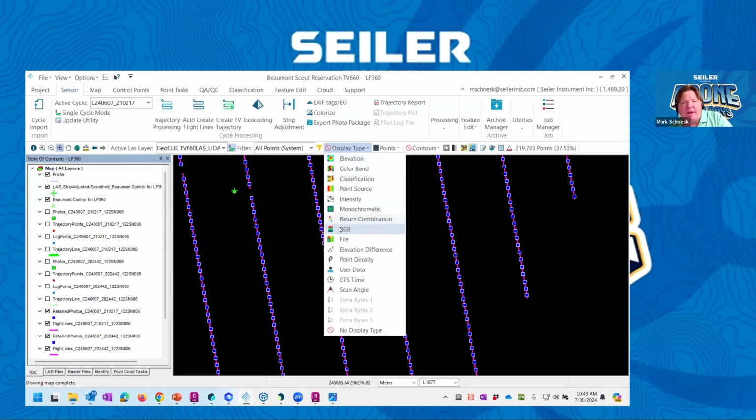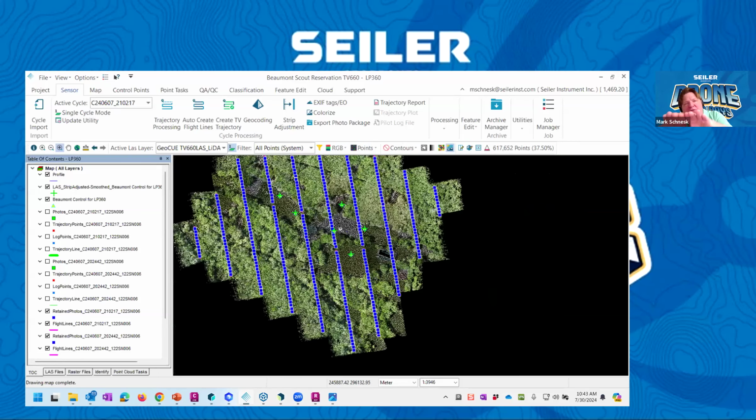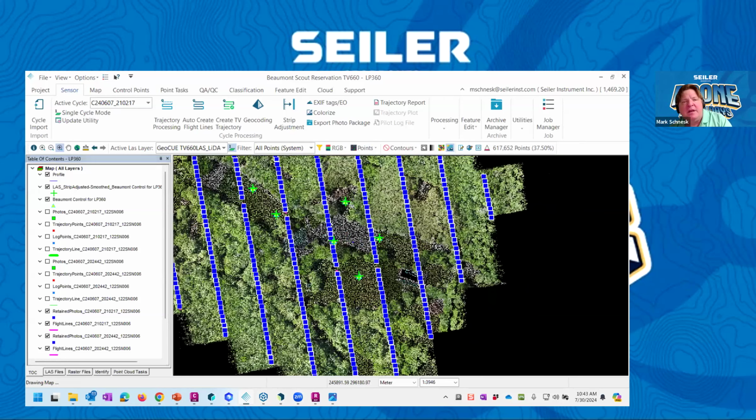Back to RGB. It'll merge those strips together. So for each flight line going this way, there may be subtle differences in the overlap area, that edge to edge elevation. And the strip alignment software lets me go ahead and merge and register each aligned strip together to get a solid. DJI Terra does it by that optimization tool that's in there.